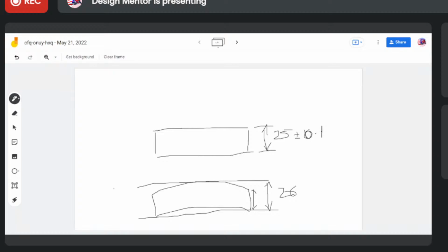Yeah. So if we keep this 0.1, so now the shaft can pass? No, it won't pass inspection. It's not correct, right? Because now the envelope should be 25.1 max, right? Otherwise, the shaft is not correct.